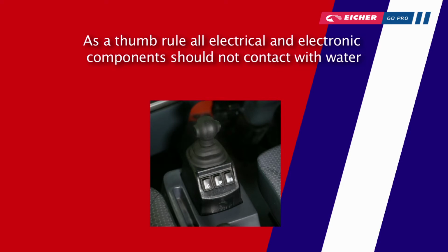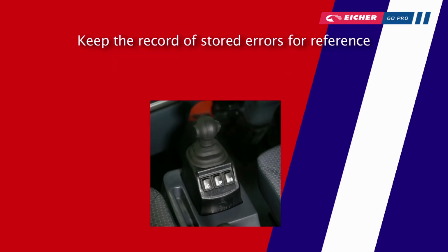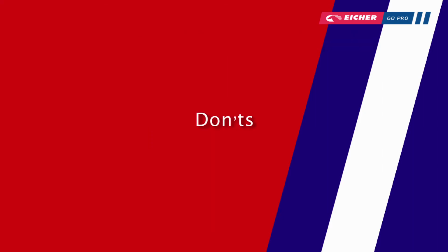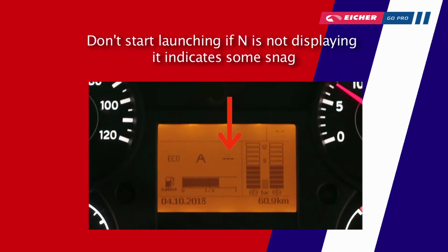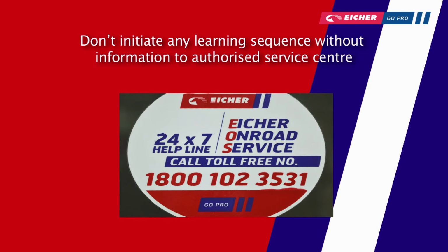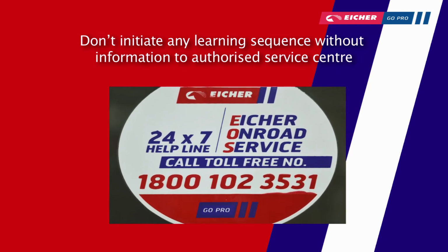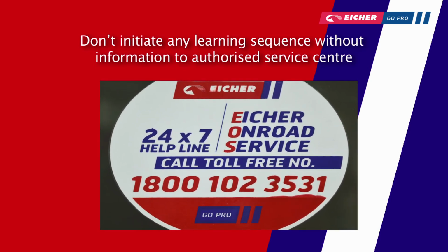As a thumb rule, all electrical and electronic components should not come in contact with water. Keep a record of stored errors for reference. Don'ts. Don't start any operation till completion of self-check. Don't start launching if N is not displayed. It indicates some snag. Don't initiate any learning sequence without informing the authorized service center.